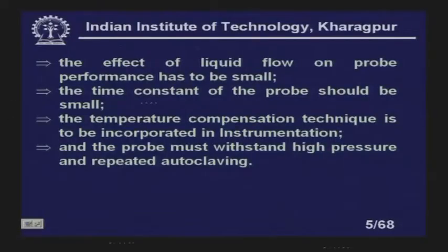Then the probe must withstand high pressure and repeated autoclaving. This is also a problem, because whenever we use sensors in bioreactors, we have to autoclave, that is, sterilize. Autoclaving is like a household pressure cooker which you have seen.